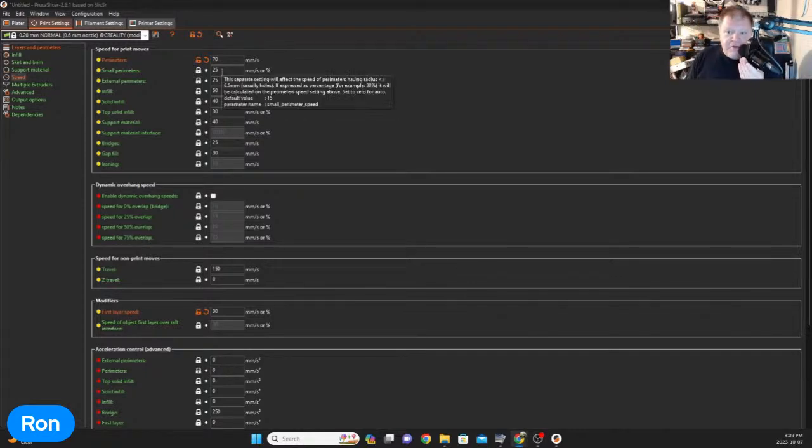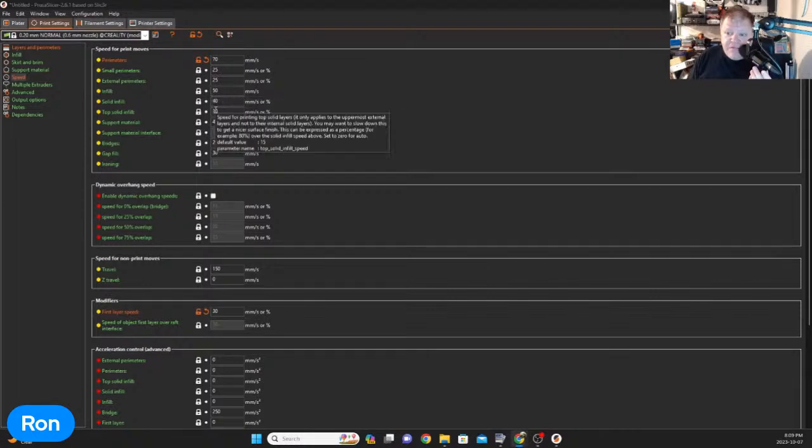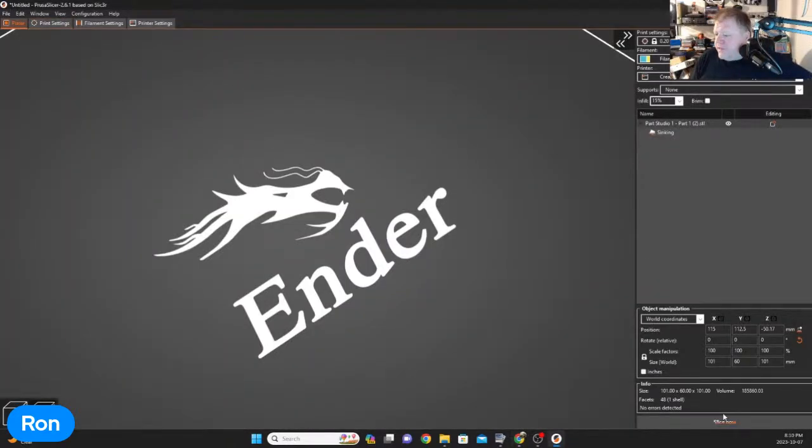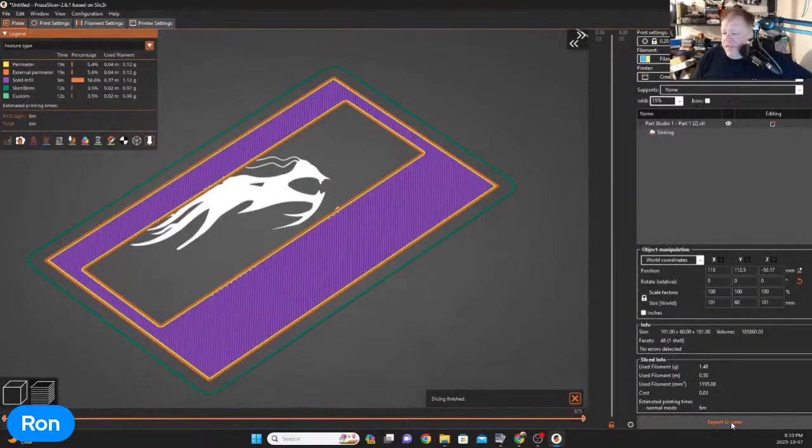Small perimeters, blah blah blah. Well, we don't really need to worry about those. 50 infill, 40 solid infill, 30. Yeah, let's go with 30. That sounds good enough. Platter, slice now, and it tells me 6 minutes. That's pretty damn good.